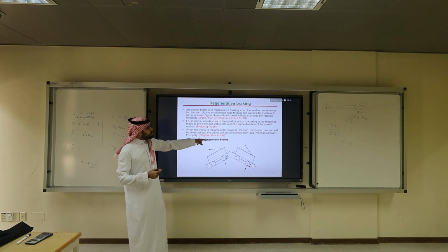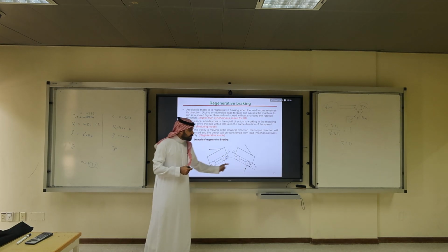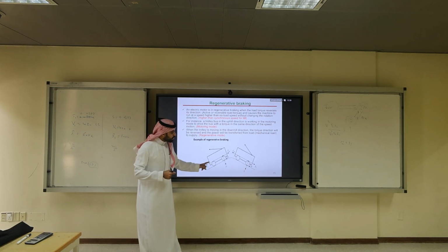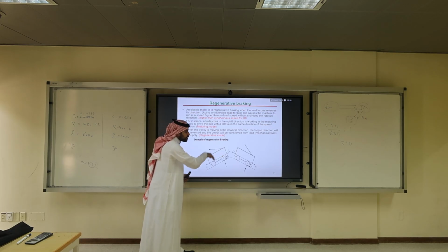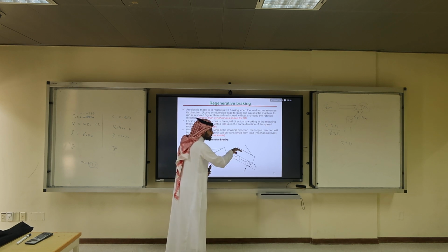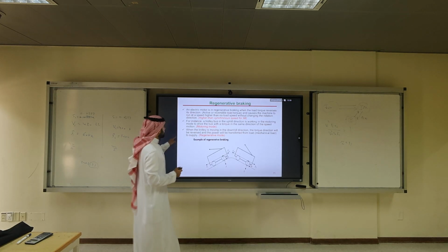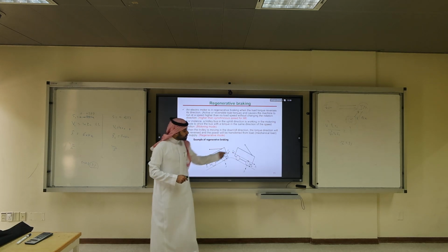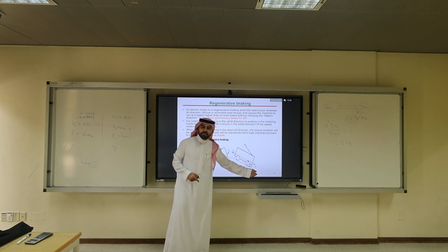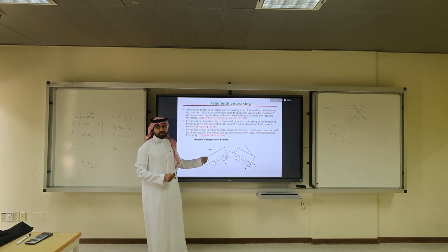So now, because it's dynamic, we can have a negative load torque. But what is the direction of the speed of the car? The car is going uphill, so omega is counterclockwise. The car is going downhill, omega is what? Also clockwise. You see it? So here we have torque that is positive, here torque is negative. Omega is positive, omega is still positive. So torque times omega, where torque is negative, is a negative power here, and a positive power here. I'm teaching you physics 101.